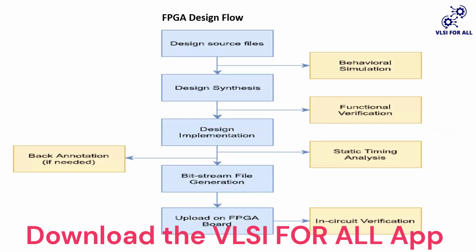These are all the steps of the Xilinx Vivado tool. Everything is given there: the simulation part, implementation, and bitstream generation. Everything we are doing is in that particular Xilinx Vivado tool. Then, whenever our final bitstream is generated, we connect it to the board through wires or flash and all. We are connected from our computer, and then we connect to the board and test it.